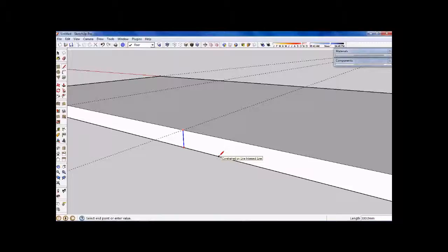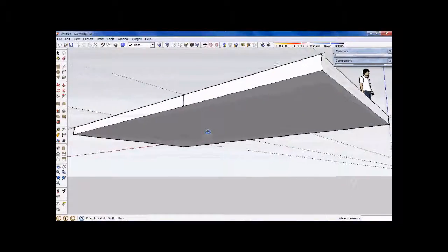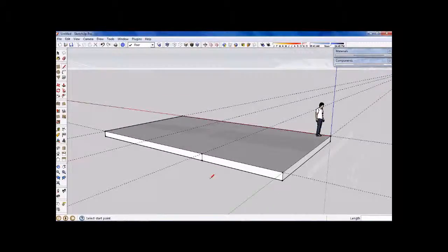Okay, now we'll just push-pull that face, what's left here, the distance that it would pop out underneath the roof eaves. Now I would say if we have a 900 millimeter roof overhang at the back of the building, I would pop this wall out a little bit less than that to enable the fascia at the gutter line to sail past the wall.